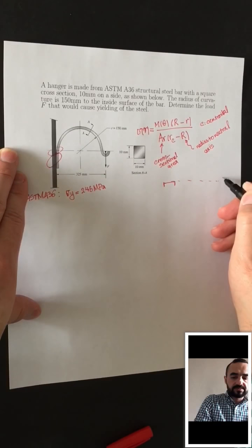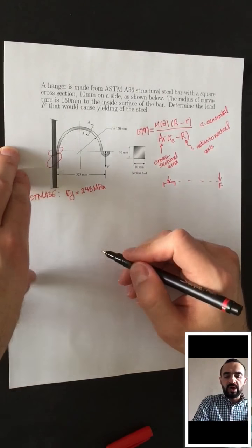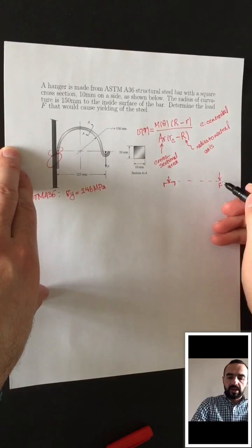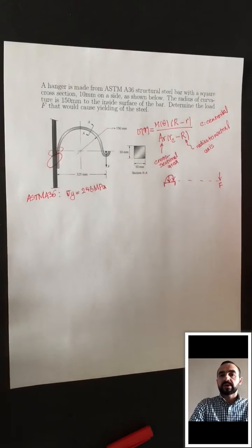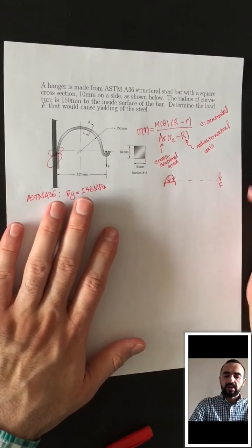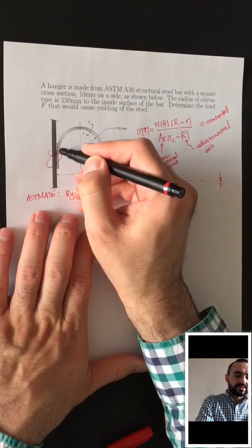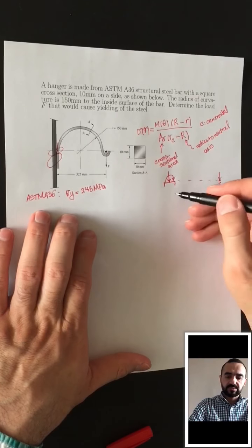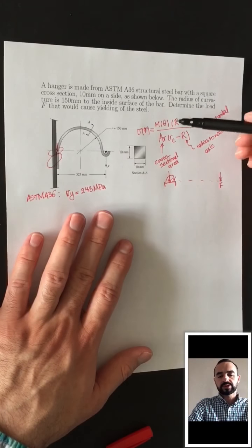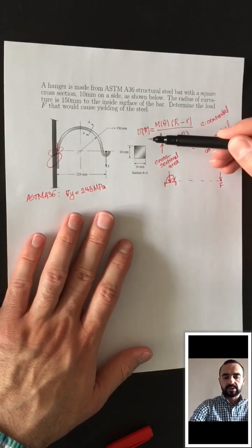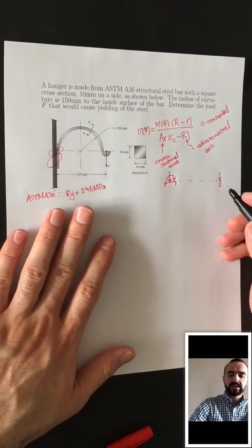we transfer the force from this point F to this point with its coupling moment. And the moment would be this moment. We use the principles of statics, and then we transfer the force from this point to this point, at the centroid of the desired section where maximum moment occurs. Maximum moment corresponds to maximum stress, and then we can set that maximum stress equal to sigma yield.